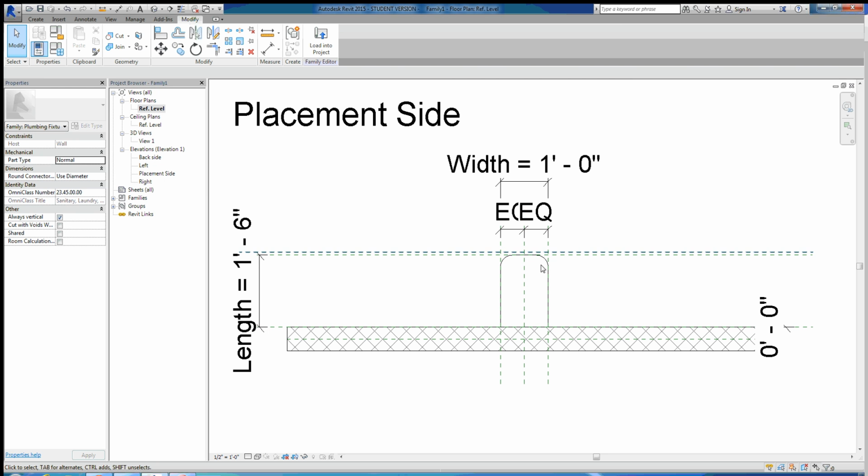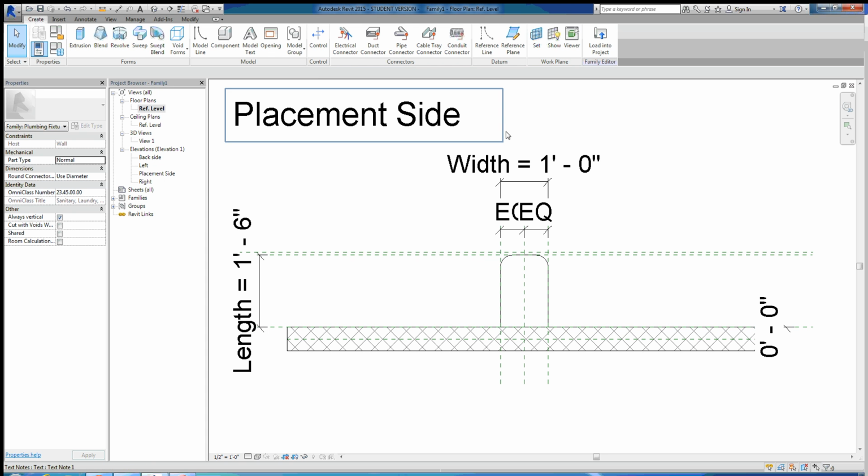Now we want to make the button coming out this way. If we want to use the extrusion command, though, we probably want to get in a different view, because if you are drawing the extrusion, you're going to draw the profile of it, and then you're going to extrude it out in the 3rd dimension. So let's go ahead and make it so that our work plane becomes this reference plane right here, the one I have highlighted. So we'll go to create,